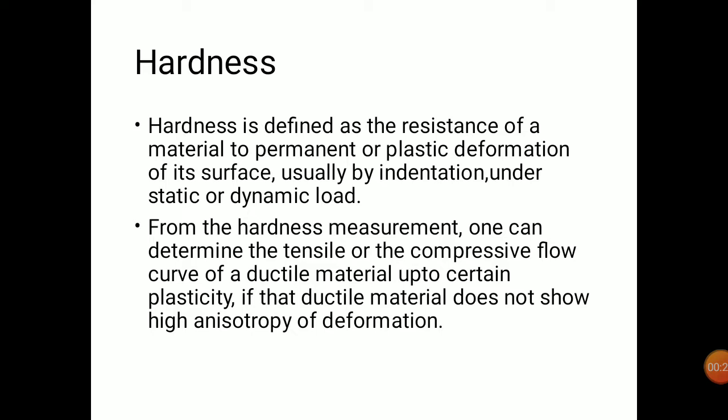Then we will see why hardness is measured. From the hardness measurement, we can determine the tensile and compressive flow curve of a ductile material up to a certain plasticity, if that ductile material does not show any high deformation. So that is the use of hardness. The hardness test is carried out for each and every material that is being produced in the industry. So we have to do the hardness test for every material.